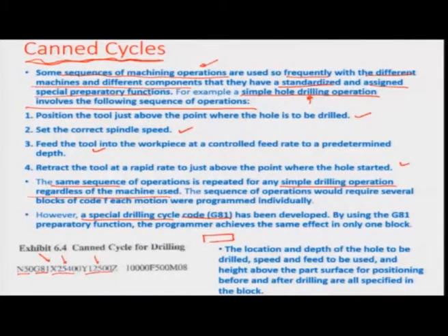If you remember, there was a block in this case and we were trying to drill from a certain point which is somewhere here, which reads 25.4 and 12.5 xy, and then going into this whole thing and coming out back, okay, and the tool was placed somewhere here from which you had to come to this particular position. So, automatically the tool from its docking position comes to this and then goes to an extent of z equal to minus 10 millimeters and comes back, okay.